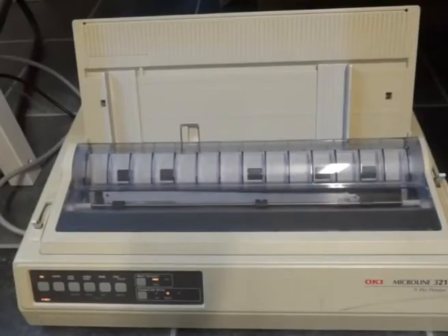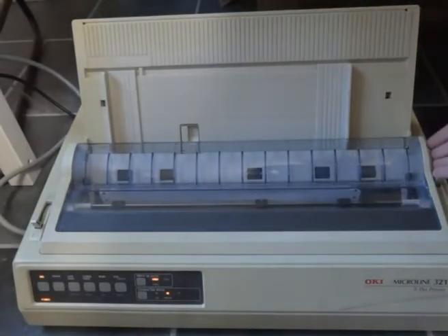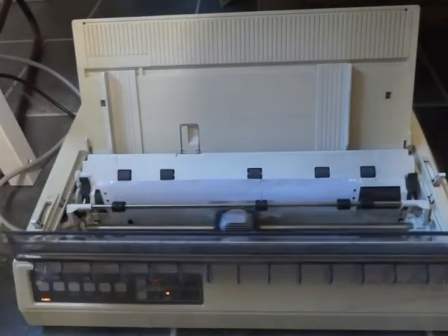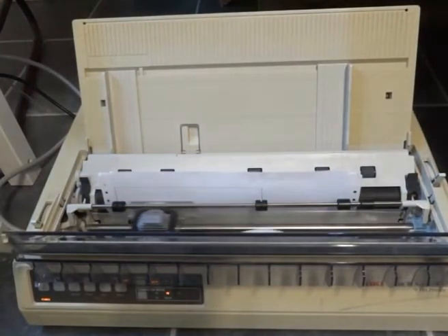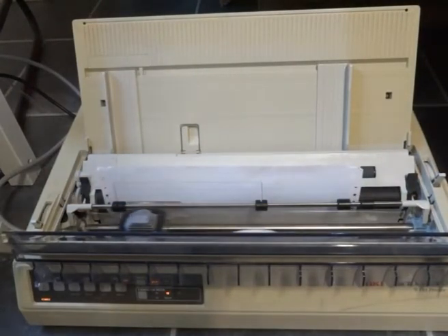Printer manufacturers soon understood that most of the print jobs had a short length of 1 or 2 pages. Note that typically each page has about 80 columns and 25 rows and can take about 1000 to 1500 characters. So, they added electronic memory or buffer memory inside the printer of say 2048 bytes or 2 kilobytes or more, which could hold that many characters in a first in first out, FIFO, queue. This memory was very fast and could absorb data at a very fast rate, typically 5 microseconds per character.